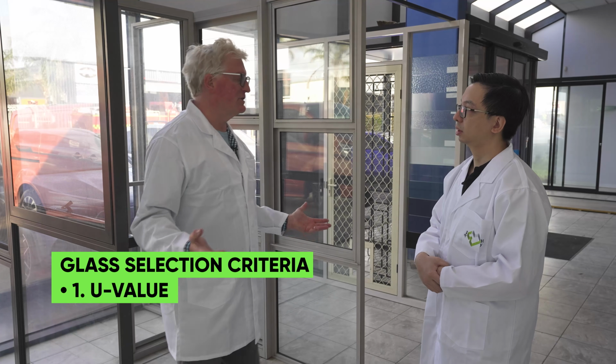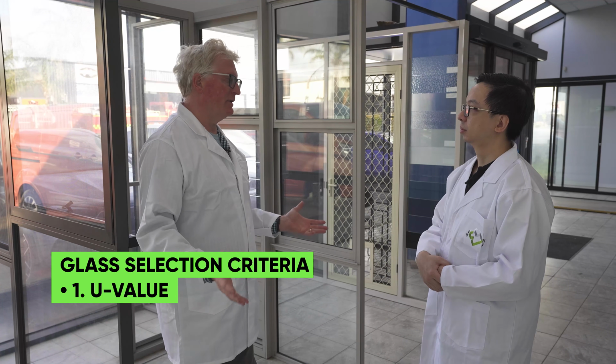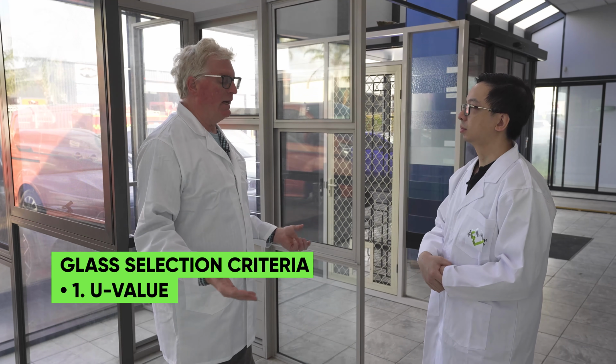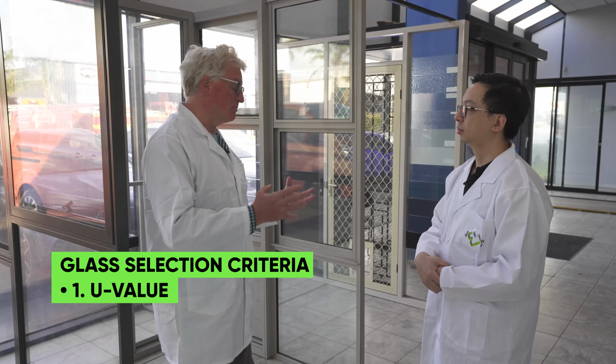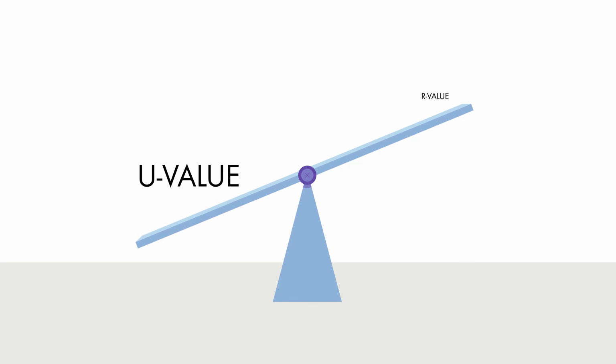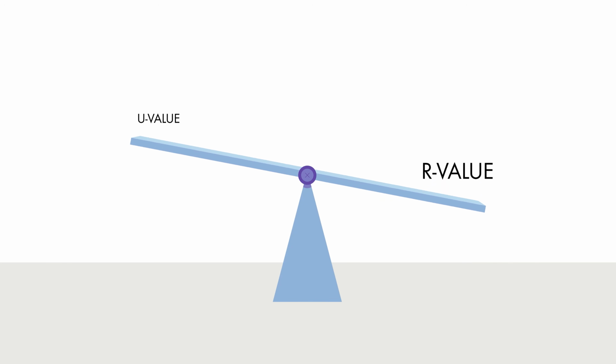Now, we all are familiar with the U value as the inverse of the R value, the resistivity in conductance. And the U value is typically the reciprocal of the R value. So a smaller U value is actually a larger R value, right?